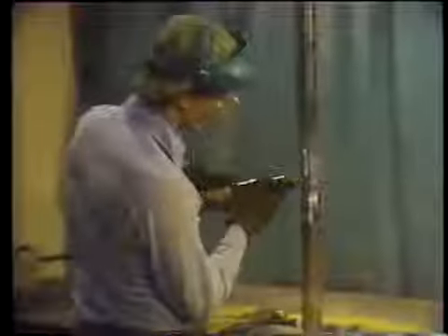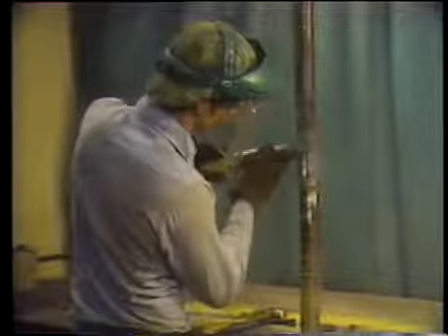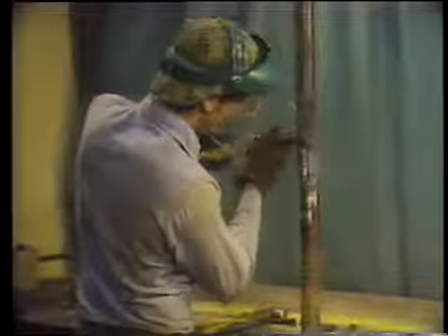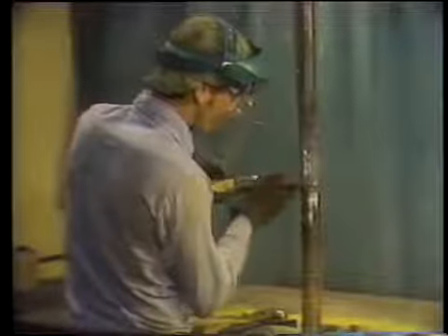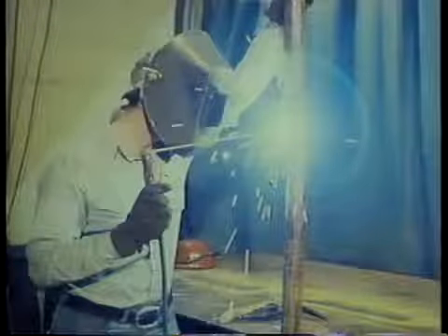Next, the surrounding tube surface is ground down to prepare it for cladding. This kind of repair is usually clad to reinforce it. Once the rupture has been closed and prepared, the edges of the rupture can be welded together. Remember, when a boiler is being repaired, the welding can only be done by a certified welder. The number of passes needed to fill the opening will depend on the thickness of the tube.